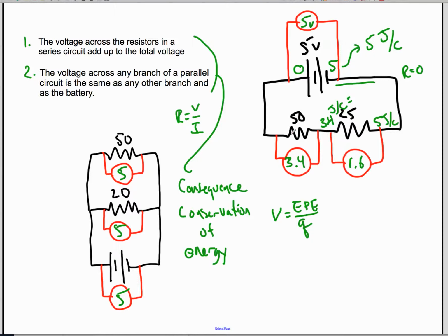Now, in the last part, we have all in here, the voltage has to be 0. That is, all the coulombs of charge that flow there have to carry 0 joules per coulomb of charge. And that is all throughout here because there's no energy loss. If we end up 0 here and there's no energy loss, this also has to be 0 volts. That is, 0 equals 0 joules per coulomb. All right, so if this is 3.4 joules per coulomb and that's 0, then the drop here is 3.4 joules per coulomb, or 3.4 volts. In other words, energy is being conserved here.